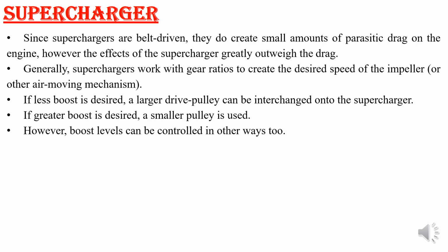If you require a very small boost pressure, like from 1 atmosphere to only 1.1 or 1.2, very little boosting pressure, then a larger drive pulley can be interchanged onto the supercharger.